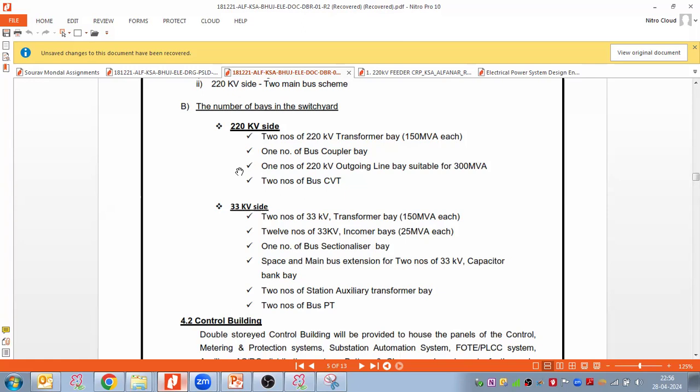No problem. So in bus A, I have one feeder that feeds my first RMU and continues to the second RMU, third RMU like that. And the last RMU goes back to the substation in the bus B section, and there is one feeder I'm using to connect to it. Now this loop is closed.